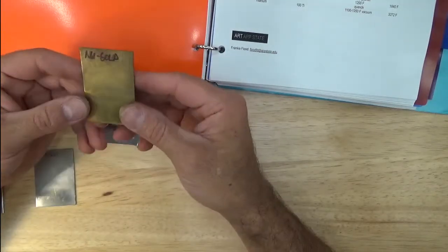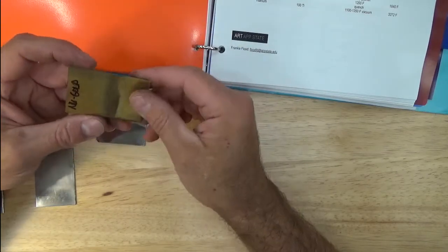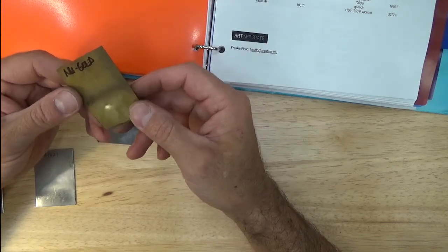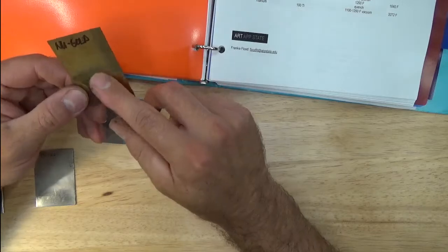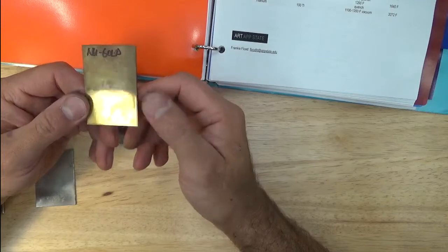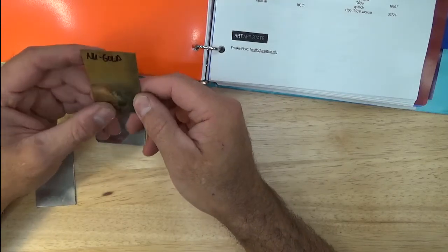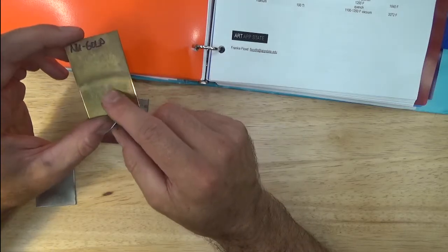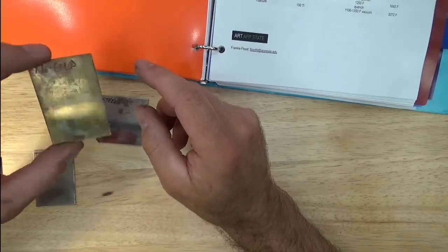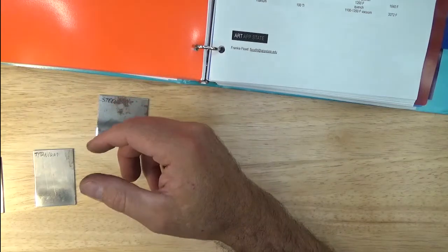New gold is listed here. There is no gold in new gold if you look at it. And on the composition sheet, you're looking at 88% copper and 12% zinc. So you don't see this used as much. When I was a student, we used quite a bit of new gold and would get it, but I don't see it being used a whole lot recently. But it just has a slightly more golden color to it. So if you are interested, I'm sure you can seek this out and get new gold. Can be silver soldered as well.